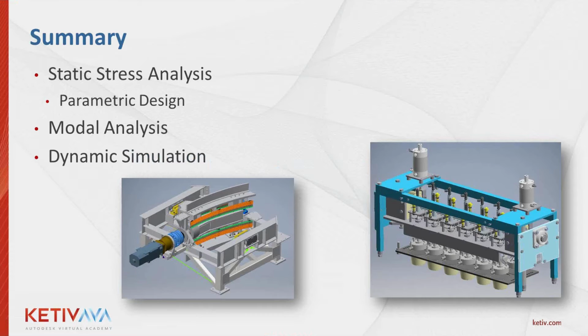And to summarize this one, we looked at doing static stress analysis inside of Inventor, where we did a parametric design without having to go back and forth and change parameters. That's one nice way to kind of look at different configurations, if you will. There is modal analysis that's available inside of there, where I showed you really quickly the interface where you can do that. And then there's dynamic simulation and frame analysis as well. So again, we'll have topics on that coming soon, I'm sure. We want to make sure we have well-rounded AVA sessions coming up, but those are things that you can do inside of Inventor.